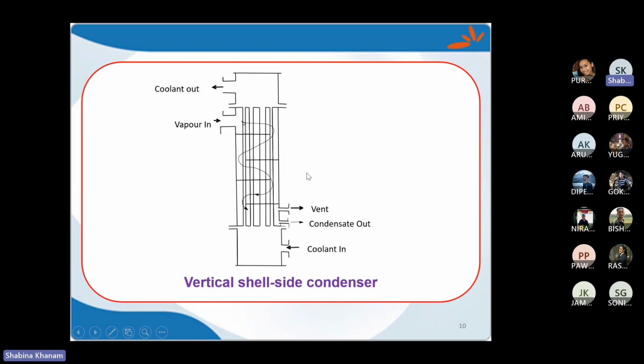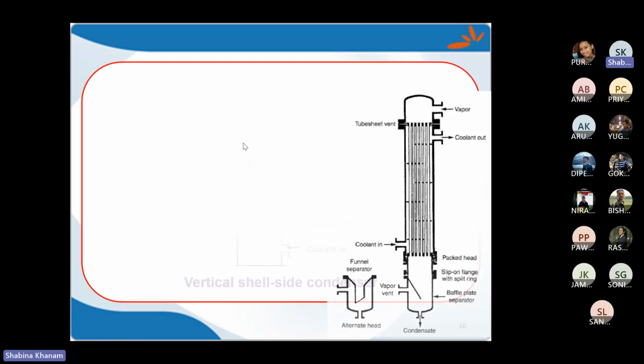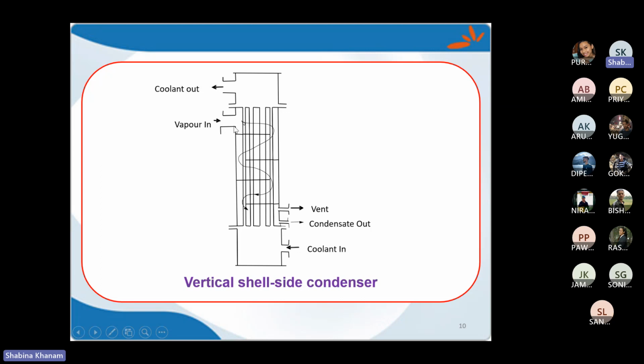Okay, not the vertical cut. So in that way we can consider this vapor inlet, and as the condensate proceeds, it brings the vapor to move down, and condensate exits from here, and above that we usually place the vent. And the steam trap will be placed over here.